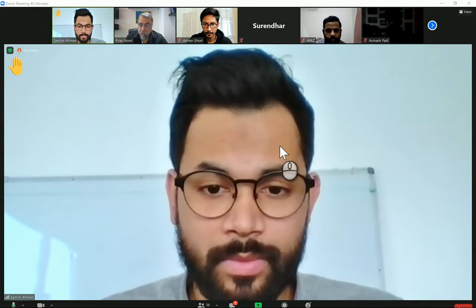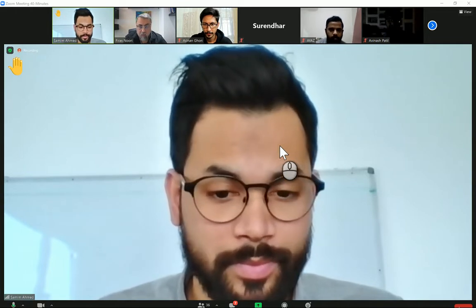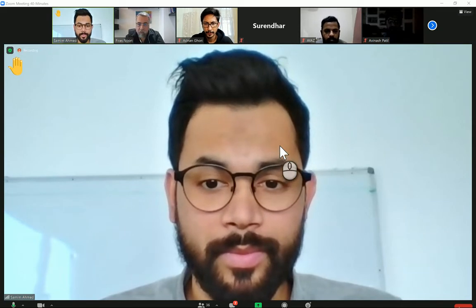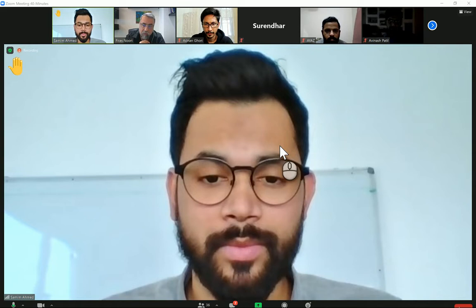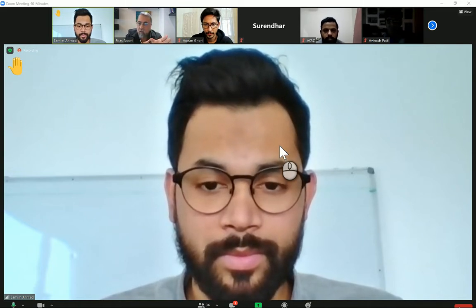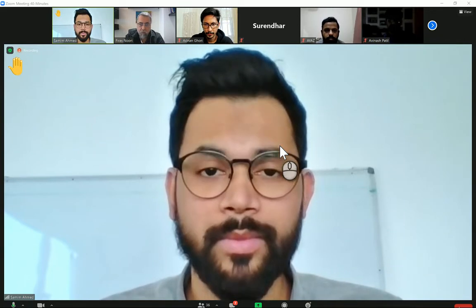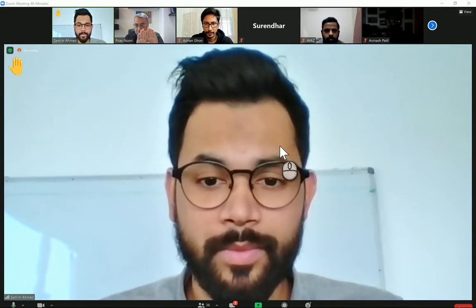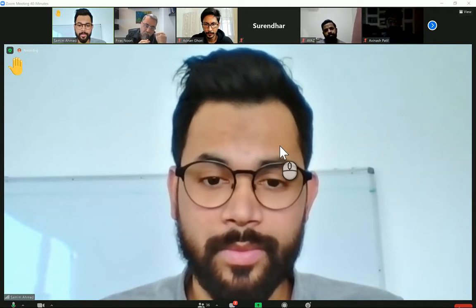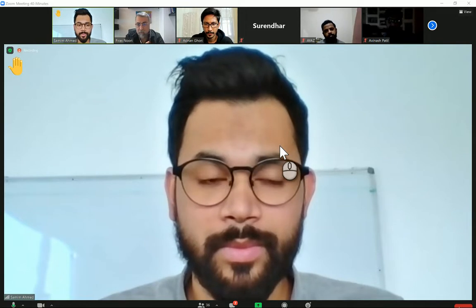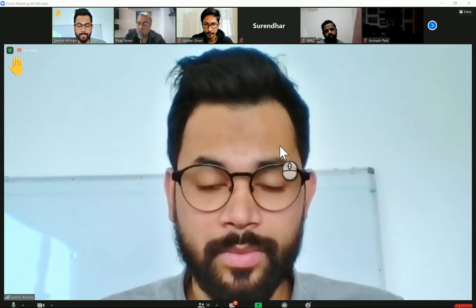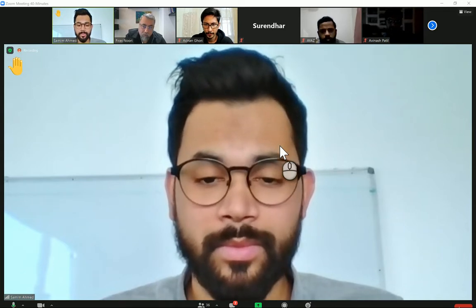The second method can build the element as a horizontal element and a vertical element, and it allows you to overlap them with the laser cutter to create a geometry that looks like the tower you want to design, for example. Or there is another plugin. I designed this plugin. It's very easy, by the way. You can design it yourself. It takes the faces and unwraps them, and gives you the overlap join and where to cut and where to scratch, so you will be able to bend it to create a 3D model. Now we're talking about two types of fabrication, the slice method and the unwrap method, and both are fully compatible with Dynamo.